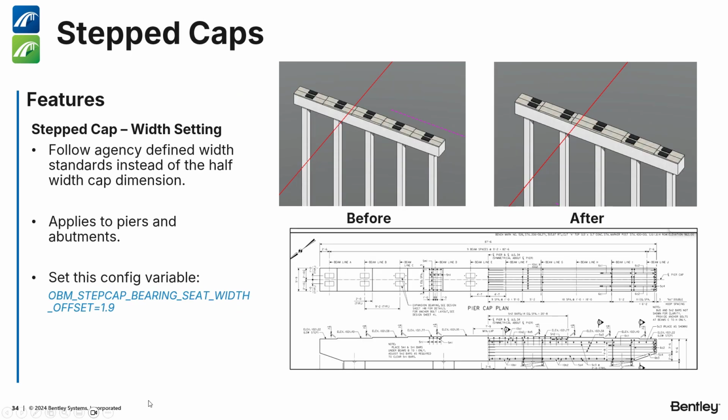For step caps, there is an option through a config variable to specify the bearing seat width for your caps. Certain agencies define that with a standard instead of the half width cap dimension that we do automatically.